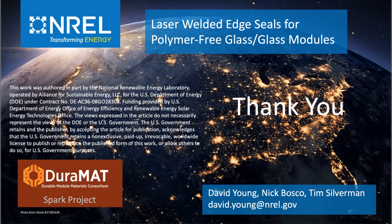But I would say pillars probably wouldn't work, and full ribs might be conservative. We did try both ribs that are welded and ribs that weren't welded, and we needed them to be welded to achieve reduced deflection of the module.